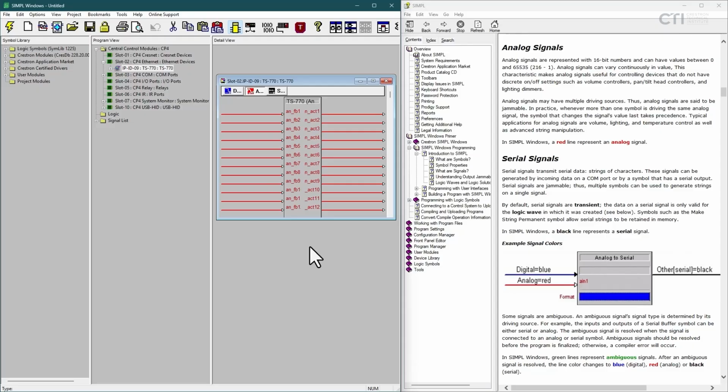Device settings. Many device parameters that require a range of values, such as temperature set points, fan speed, or video input selections, are managed using analog joins in SIMPLWindows. Feedback and monitoring. Analog data types are also used to provide feedback from devices, such as reporting the current temperature, lamp hours on a projector, or the current position of a motorized shade.